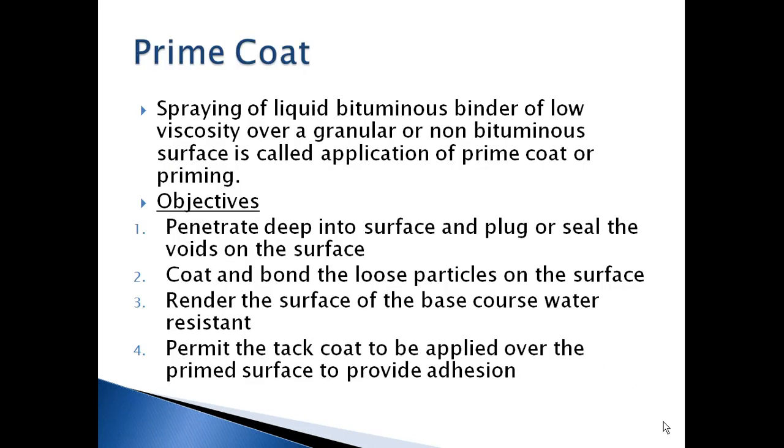Let's see what is a prime coat. Prime coat is nothing but spraying of liquid bituminous binder, which is of low viscosity, over a granular or non-bituminous surface. This is the application of prime coat.